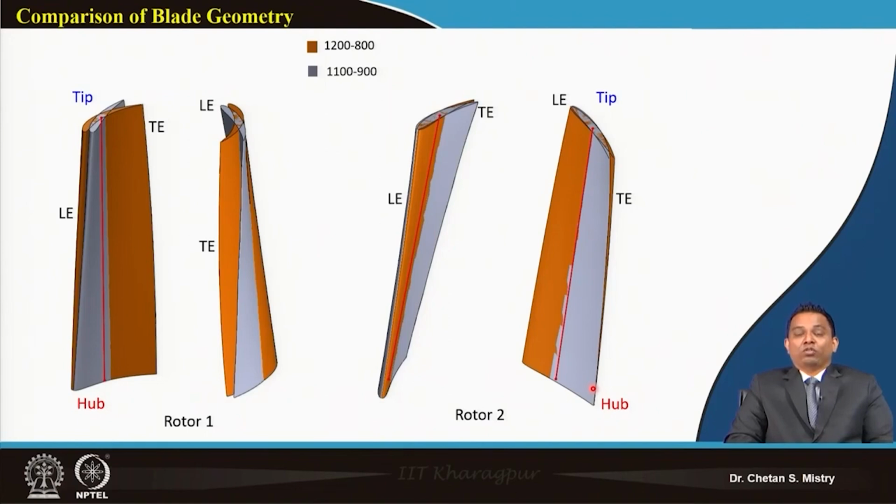Okay, and as I told, in one of our latest publications we have a study of the distribution of total pressure ratio between two rotors, and when we are loading our rotor 1 too high, you will have more chances for your flow to get separated near the tip region, and that will make the design more challenging. So maybe you need to go with slightly higher loading for rotor 1, not too much loading. And the advantage of having higher loading of rotor 1, we have realized, is that it gives me stall free operation, and that increases my overall operating range.